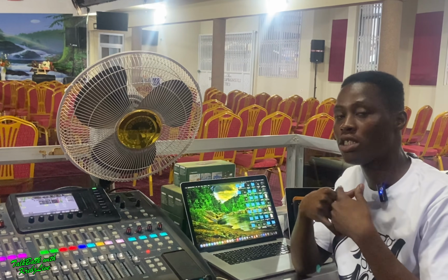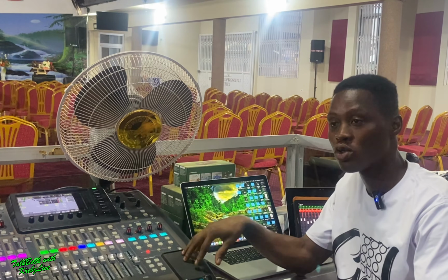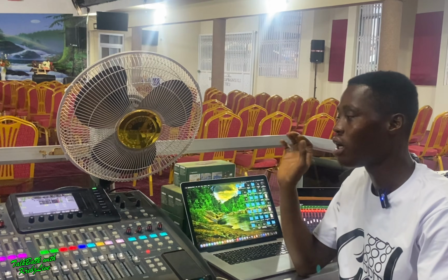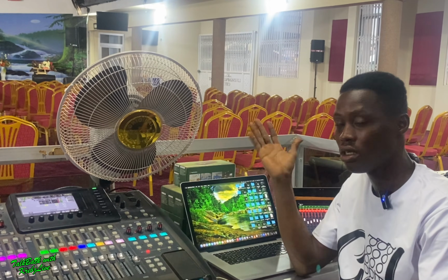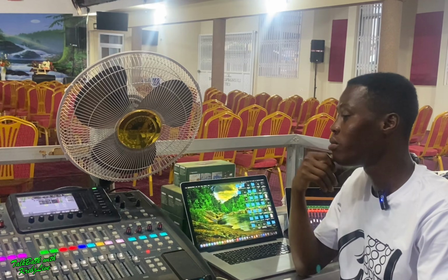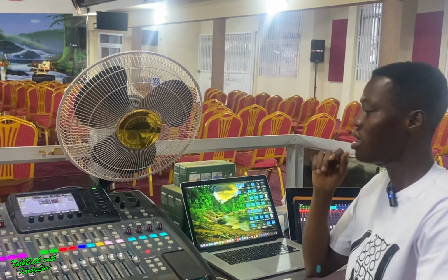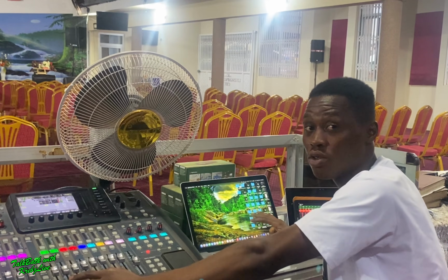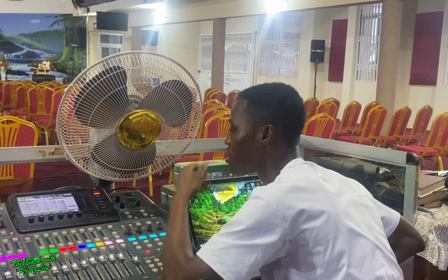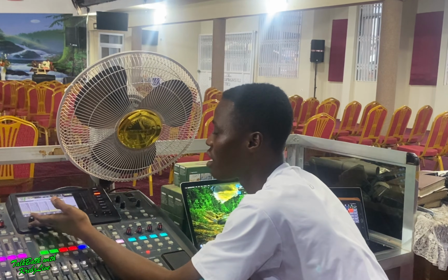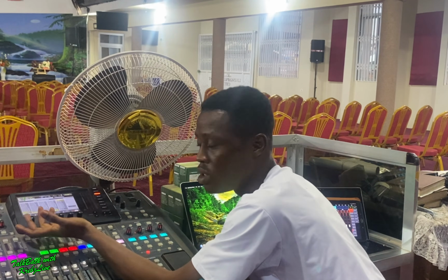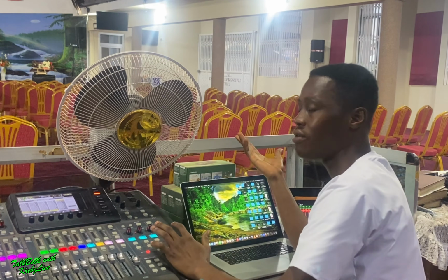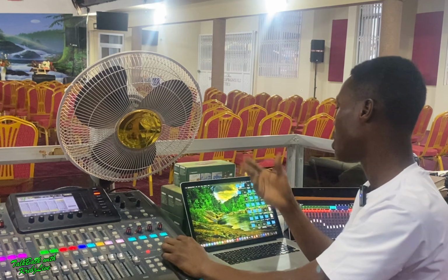Now, because in my church we are using the X32 console, which is fed by the X32 stage box, our routings are on AES50, and we're using the B side of it. So what I'll do is, the idea is to transfer everything that is on the board, or route everything as it is on the board, onto the digital audio workstation. So now I'll come to routings on the board, and then I'll check if the routings are as they are supposed to be. We said at the back of the console, direct is a local. If you're using any AES50, that means you're using a stage box. And so that is that. So I open